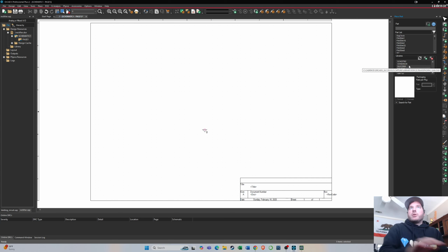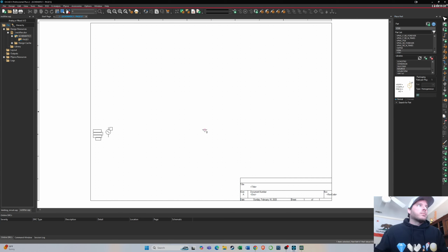Okay, next I'm going to add a source. So I just click here again and just type source. And pick whatever type of source you want. I'm going to be using a sinusoidal voltage source. I'll place this here. I'm going to mess with the parameters in a minute. I like to get all my components on the screen first.